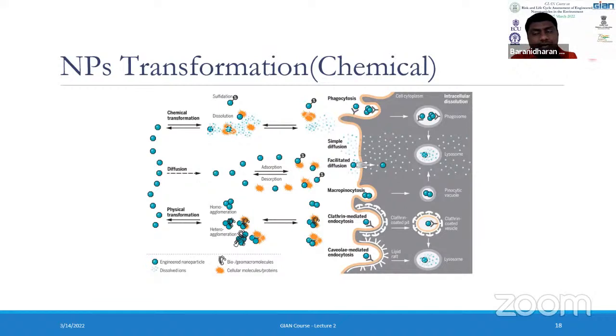So when it comes to surface as well as subsurface water, in natural, well aerated waters, normally when exposed to the atmosphere, the oxidation process is very dominant compared to the others. In an oxygen depleted environment, mostly inside sewer systems where you don't have much oxygen, such as carbon rich sediments and groundwater, reducing reactions will be there. So where oxygen is naturally abundant, oxidation reactions occur, and when there is not much oxygen, reduction reactions occur.